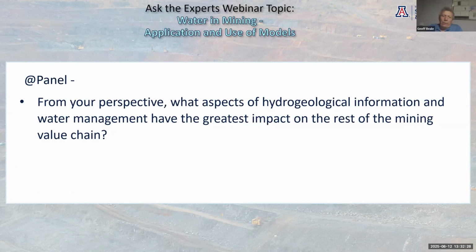And then one thing to build on what Blair was saying, for geotechnical analysis, it's really important that we focus the hydrogeological information on the defined zones of deformation or the critical failure surfaces.